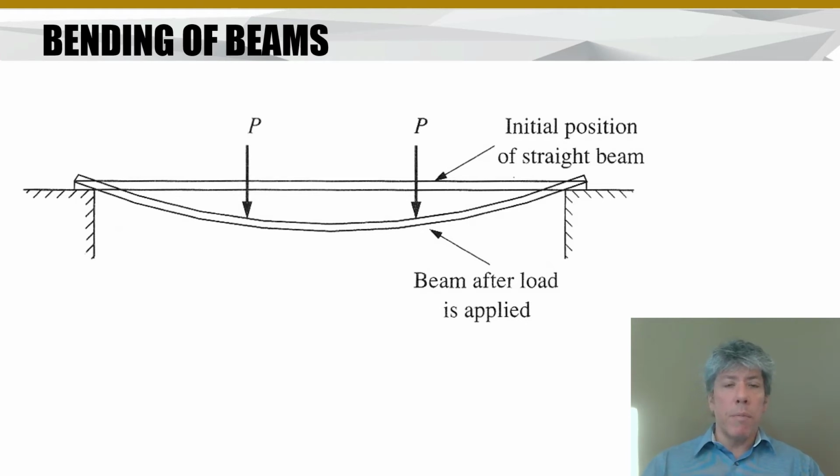But certainly a beam bends in order to support the load, because what happens is when you apply a load to the beam and the beam deflects, stress is developed within the material, and it's that stress that generates the moment in the beam and the shear that supports the load, or supports the required static load to compensate for the external applied load.